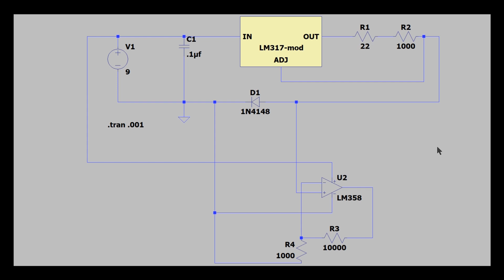Everything is times 10. So if it read 6.21, it's actually not 6.21, it's 0.621. You just move the decimal point over, and that allows you to separate very fine differences between the diodes. So it's just a workaround. It's just a lazy workaround to allow me to use a very inexpensive little AliExpress, Amazon type meter to pop in there. And you'll see this as we go forward.